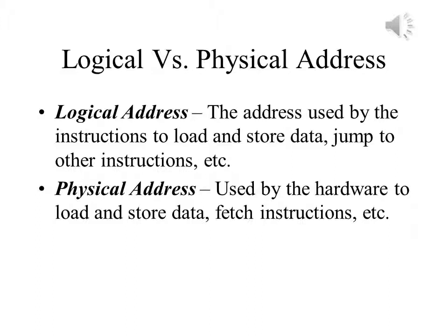By allowing the base address to change and referring to it indirectly, the exact location of instructions and operands can change as the program is loaded into different areas of memory without the program losing its ability to find its way. The physical address is the address used by the computer's hardware to locate data and instructions that it's fetching and the locations to which it will store data.